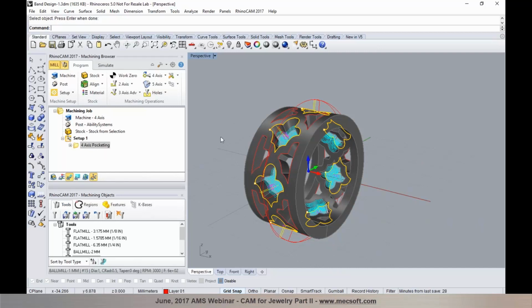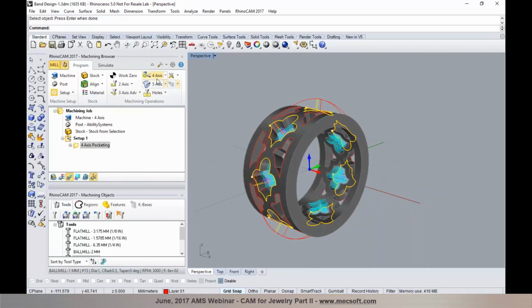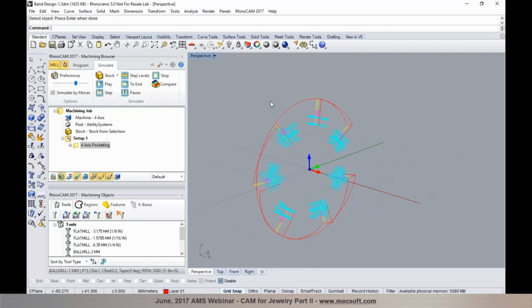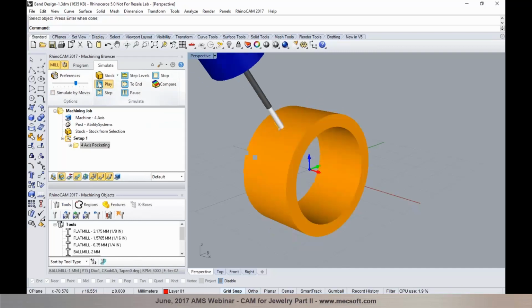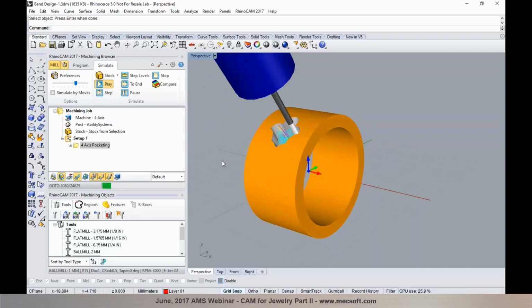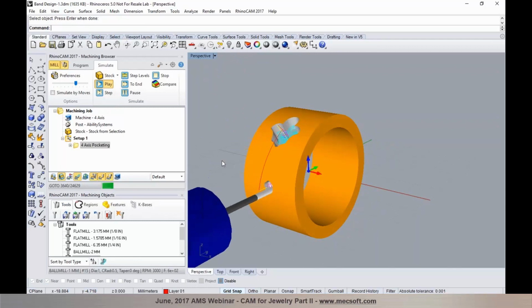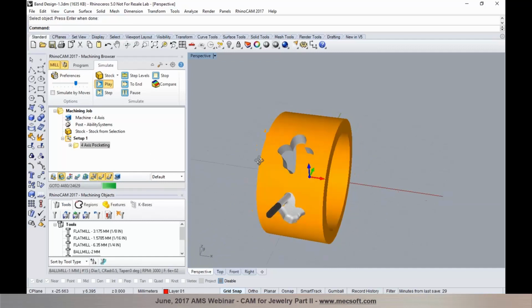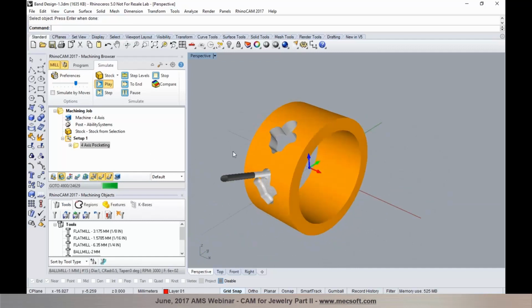So the 4-axis pocketing toolpaths are generated, and also your rotations are automatically computed. The degrees, the angles are automatically computed. So when we post-process the toolpath, you'll be able to take a look at the posted output, which shows the angle values as the part is being rotated on the rotary axis. And since I chose depth first on the cut levels, the pockets are basically programmed to the total depth before it goes from one pocket region to the next pocket region.